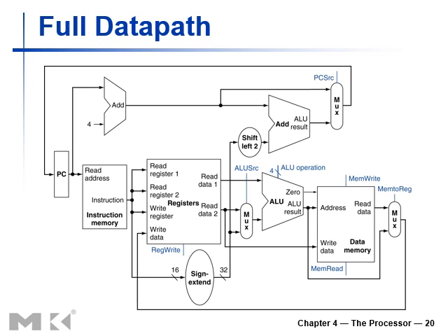Right now, discussing the full data path here. So this is the fetch section that consists of the program counter, the adder, and the instruction memory. The 32-bit machine code is fetched, and definitely later on some additional modules are added in order to update the program counter. We'll discuss that later on.